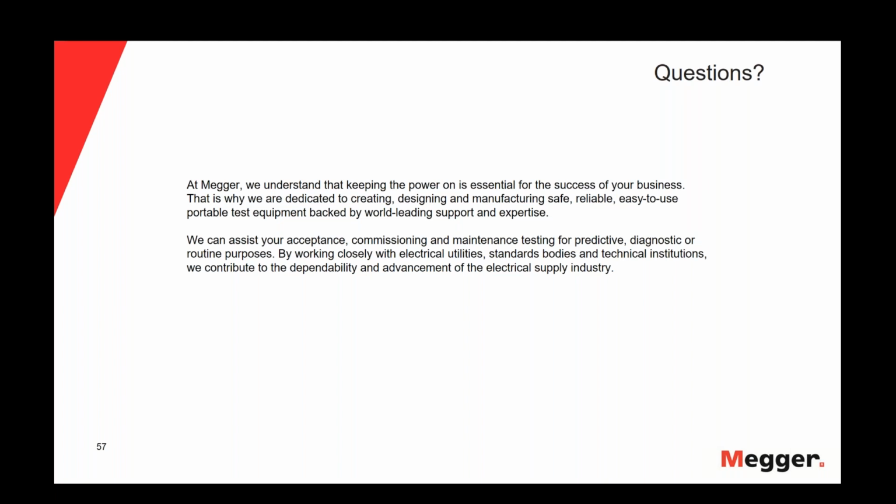S1, that's the full length, and that contains the test parameters for VLF testing. And in line with this is the German VDE 0276, which is the VLF standard for Germany, where all of this actually originates.